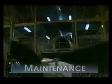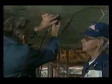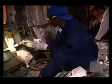Whenever an aircraft is down for a longer period of time to perform maintenance, your mechanic should take the opportunity to implement corrosion prevention activities. Perform more extensive visual inspections on those areas which you have identified as corrosion prone. Consider using non-destructive test methods, such as eddy current, if they are available. They will more than pay back the cost of the equipment. Extended periods of maintenance are also an excellent time to repair any corrosion damage found and perform prevention activities such as touch-up of damaged paint.